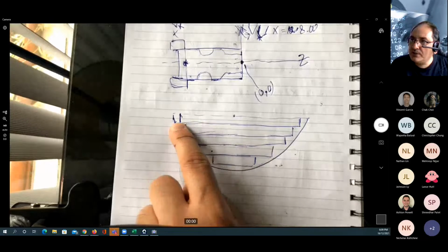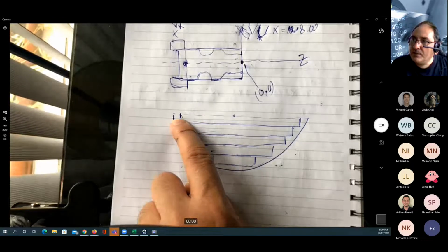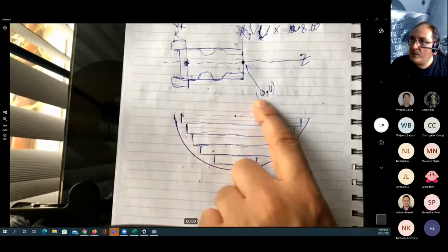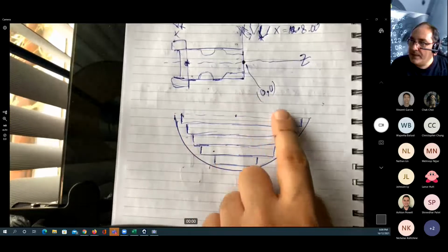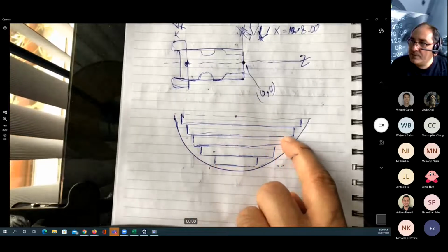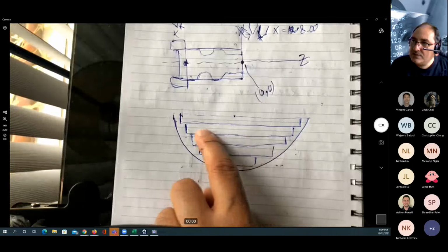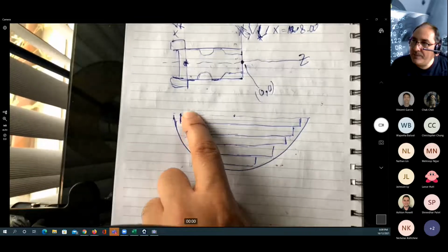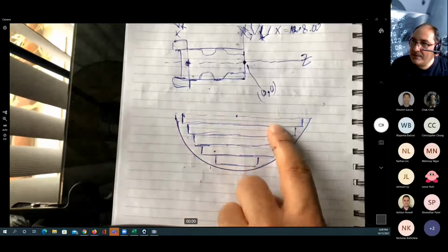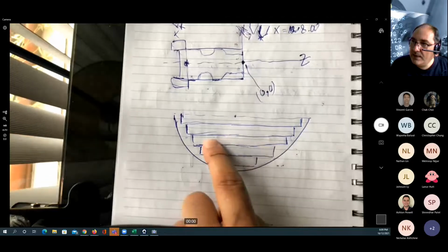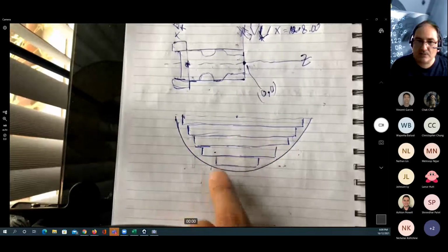Move it G01 to here. Then we go up, we go all the way here. We get down to the next depth of the cut, G01, go up, travel back, cut the third level, and the fourth level, and so on.